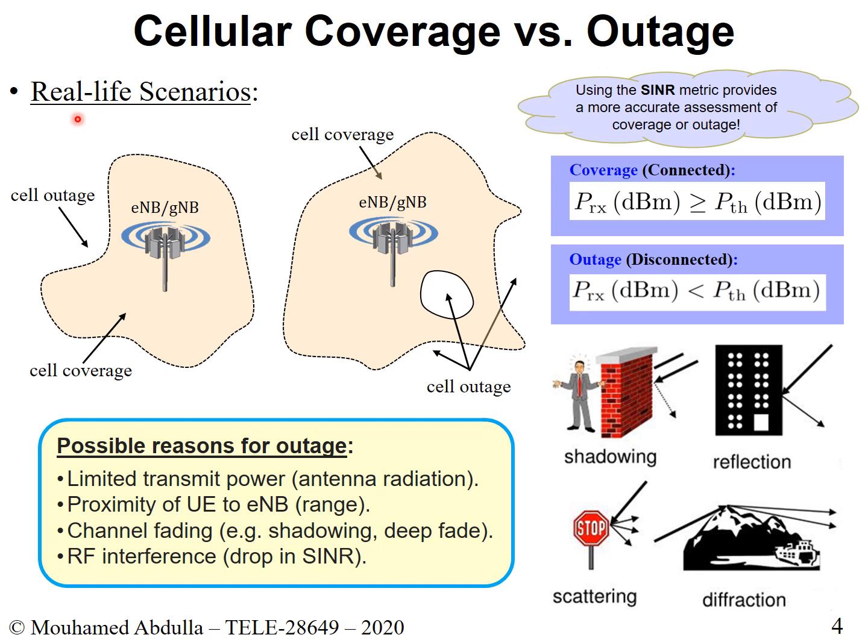So what you could end up doing is either estimating what the aggregate interference is, and then come up with some estimate for it, and then figure out the SINR and then identify if your SINR at the receiver is above a certain SINR threshold. So that's one way of doing it. Other way of doing it is simply to look at the receive power, to look at the threshold, and that's it. And then to perhaps take into account path loss and to take into account shadowing.